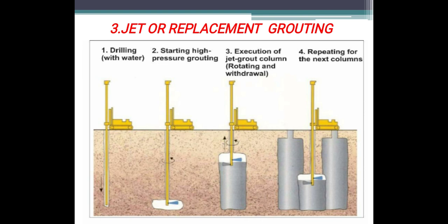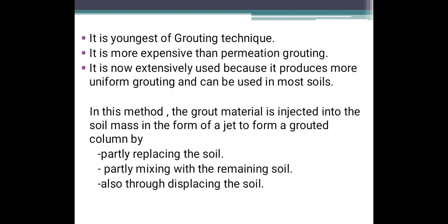and rotated and withdrawn. The third step is execution of the jet grout column, rotating and withdrawal. Fourth step is repeating for the next column. So this is the jet or replacement grouting. It is the youngest of grouting techniques.